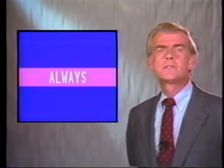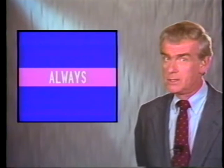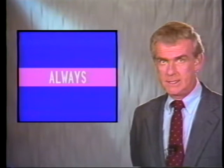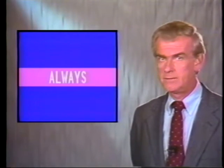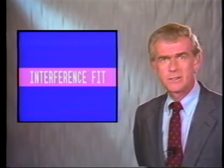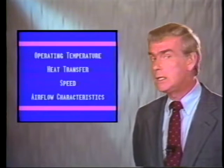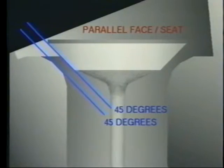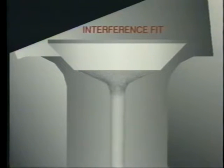You may have noticed the use of the weasel word always in two of our responses. In this case, they made our job easier. There are two basic types of fit used when designing cylinder head valve angles: parallel fit and interference fit. Factors such as valve operating temperature, heat transfer, speed, and airflow characteristics must be taken into consideration. Parallel fit means the valve face angle and the valve seat angle are parallel or identical. Interference fit means there's a 1/2 to 1 degree difference between the valve face angle and the valve seat angle.